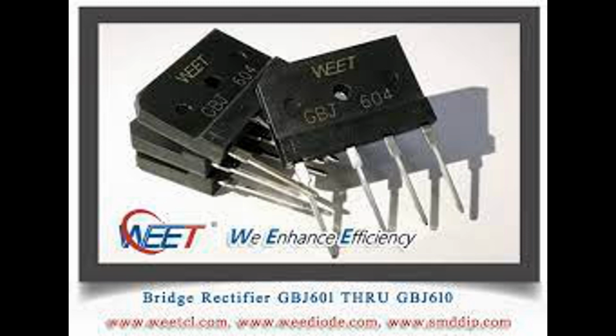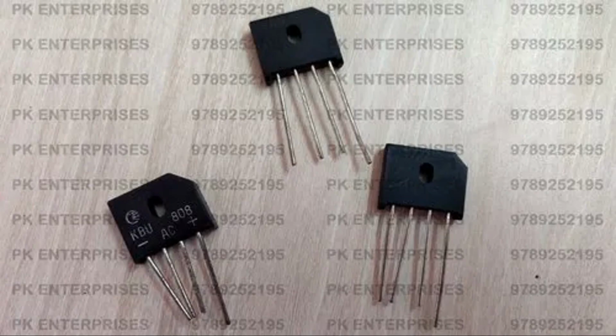In motor drive systems, bridge rectifiers serve several crucial functions, primarily related to converting alternating current, AC, power into direct current, DC, power to drive the motor. Here's how bridge rectifiers are used in motor drives. AC to DC conversion. The primary role of the bridge rectifier in motor drives is to convert AC power from the mains or another AC source into DC power. This rectified DC voltage is then used to power the motor drive circuitry.